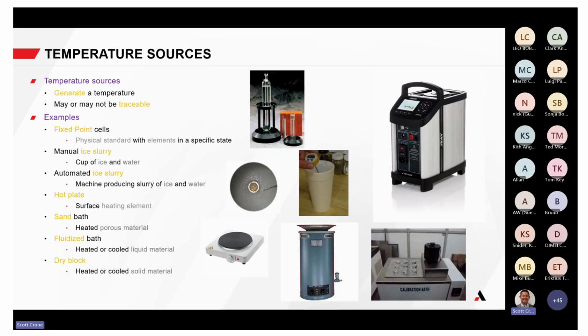Now, what we have seen out in some areas is somebody using a cup with ice and water and calling that a 0 point. It's not uncommon. We see it out in the field a lot of times. It's a lot easier with a Yeti that they have now, because those hold temperature for a little bit longer. But the problem is it's going to striate. You're going to get levels of different temperature within that cup, and you don't always know what impurities are in there. So it's not typically going to be an actual 0 point.